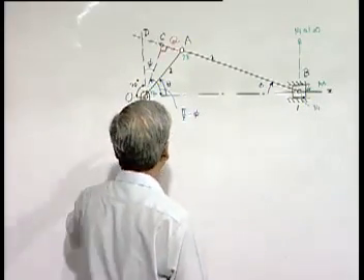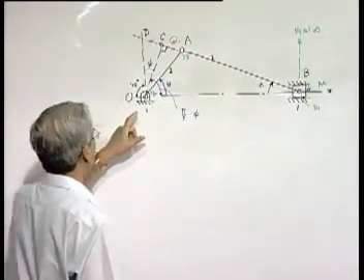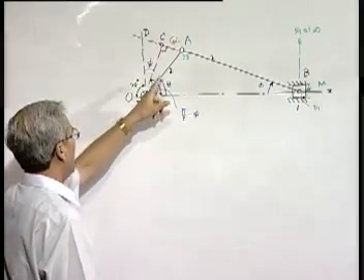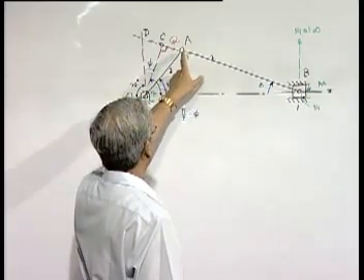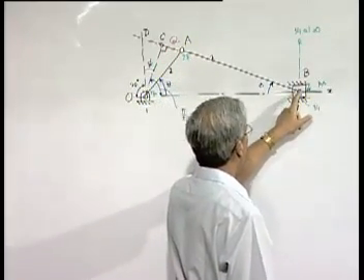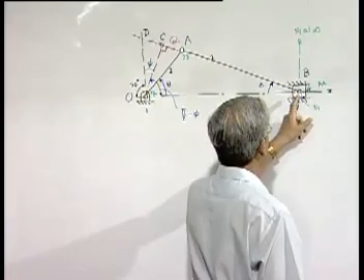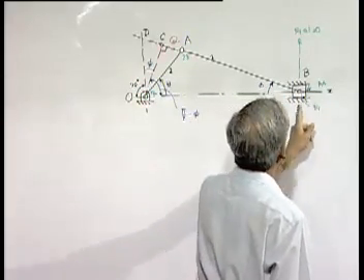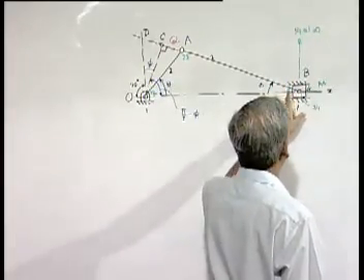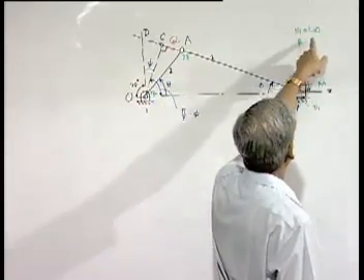So, directly we get the relative instantaneous center between link 1, that is the frame, and link 2 as this hinge. Between 2 and 3 is this hinge, between 3 and 4 this hinge, and the relative instantaneous center between the fixed frame 1 and 4 will be at infinity in a direction perpendicular to the axis x as indicated here.